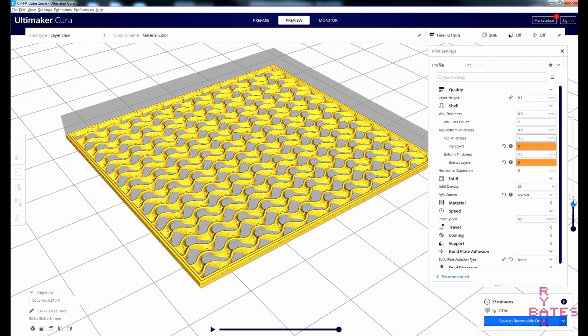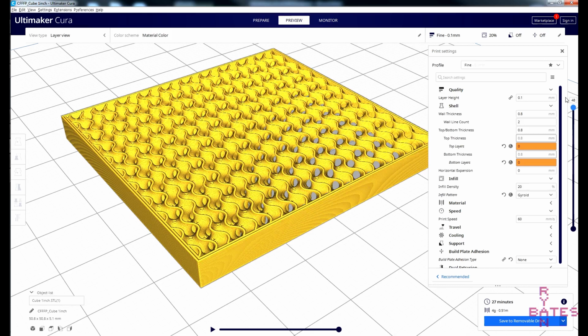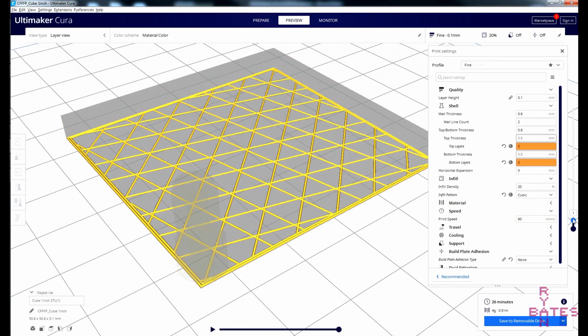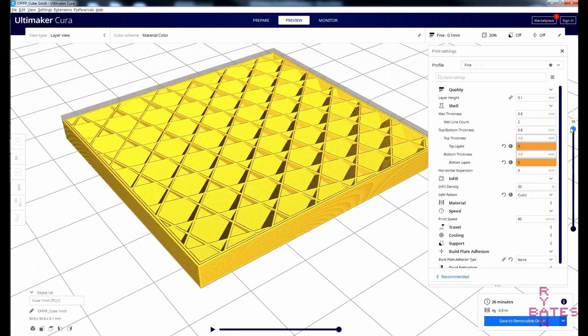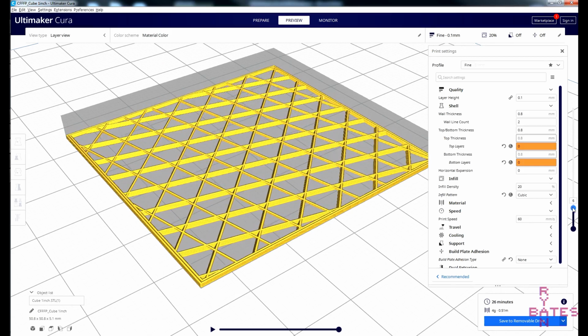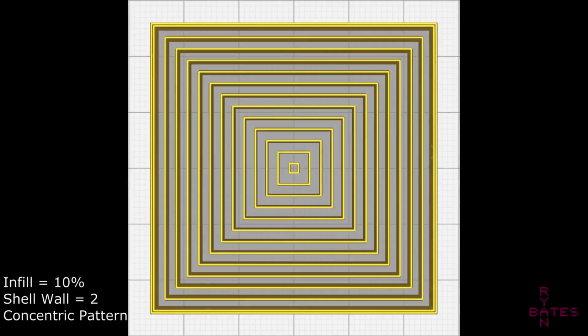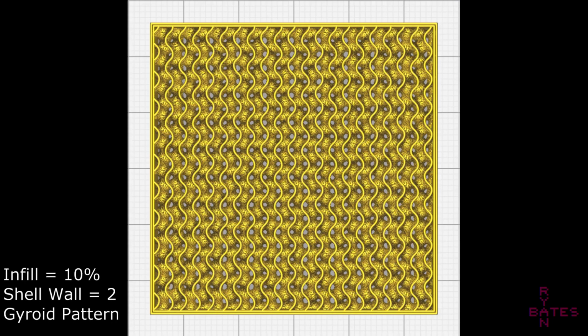Lastly, and this is more for the wow factor at the novice level, these are infill patterns. Note, not all slicers will support the option for infill patterns. The effects of infill patterns are more influential based on the overall geometry of your part. Just note, some of these patterns can inflate your G-code file significantly. And on lower end printers, these complex patterns might just result in headaches rather than a successful print.